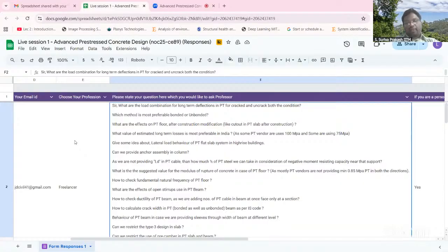And the performance of PT flat slab system has been quite adequate, but we have to make sure that they have the capability to deform laterally without compromising its load transfer in the vertical direction, right? So, though you don't have a beam, a part of the slab will act as a beam. So that will help in the load system, right? Hope it throws some light on what you are asking.